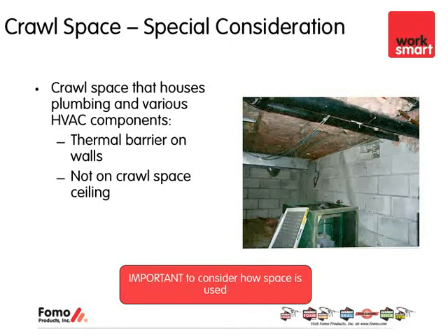In the case of this picture, you see you've got your HVAC unit, your furnace unit, down below, and it looks like mold and mildew up on the top of the crawl space. So that's actually pulling air from the crawl space up into the living conditions, again providing poor indoor air quality.